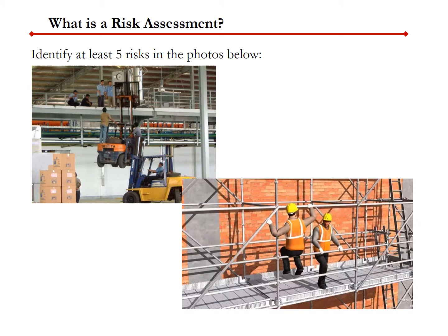You could see here unsafe practices, where they are trying to lift an object but not doing it in the proper way. Here you can see this guy sitting on the railings of the scaffold, which is not meant for that, without any harness to be anchored to a fixed point on the scaffold. This other guy is standing there discussing, which is not what the scaffold is meant for. It's meant for them to do the tasks they are supposed to do while taking safe measures, and then to come down once they are done with the task.